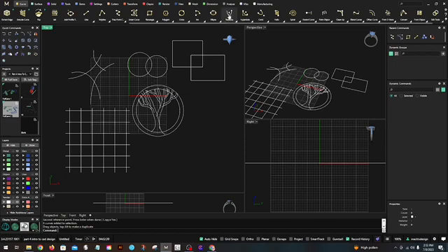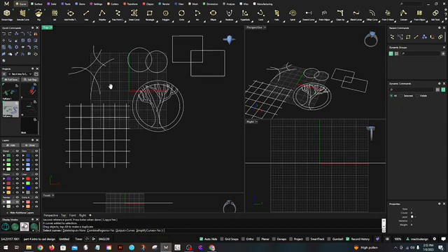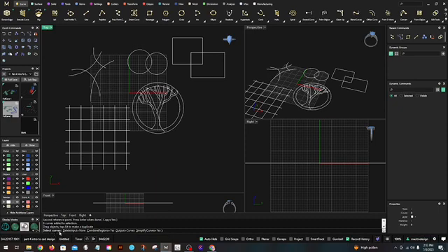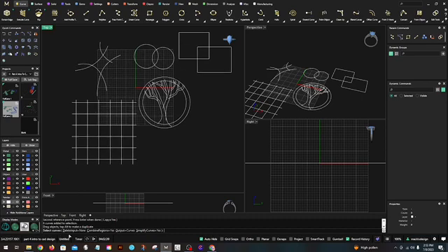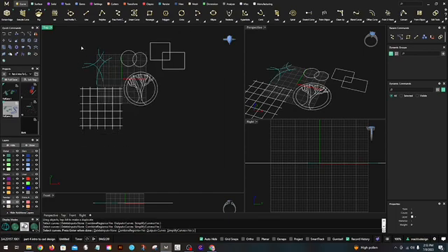Okay, curve boolean works this way. We're going to go up here, we're going to select curve boolean, and you want to select the curves, and do you want to delete your input? I usually don't delete my input, because if I want to maybe use them again for another purpose, I want to be able to go ahead and have that there. So what I will do is I am going to turn these all on a different layer. I'm going to turn them on the bright blue.